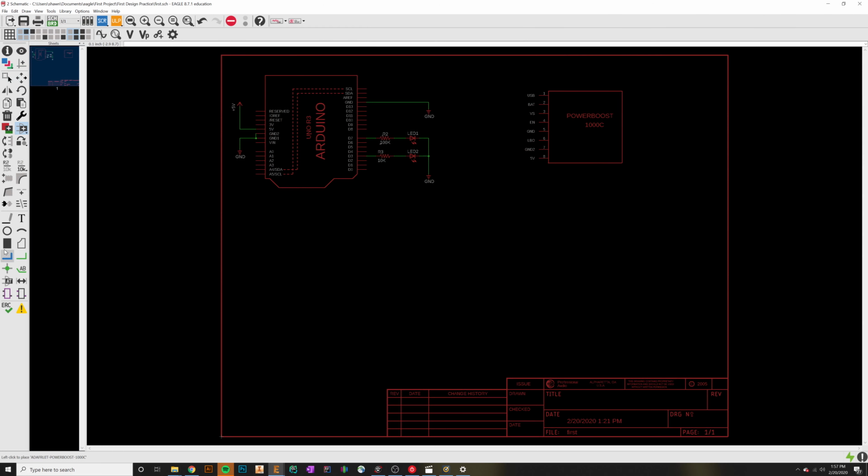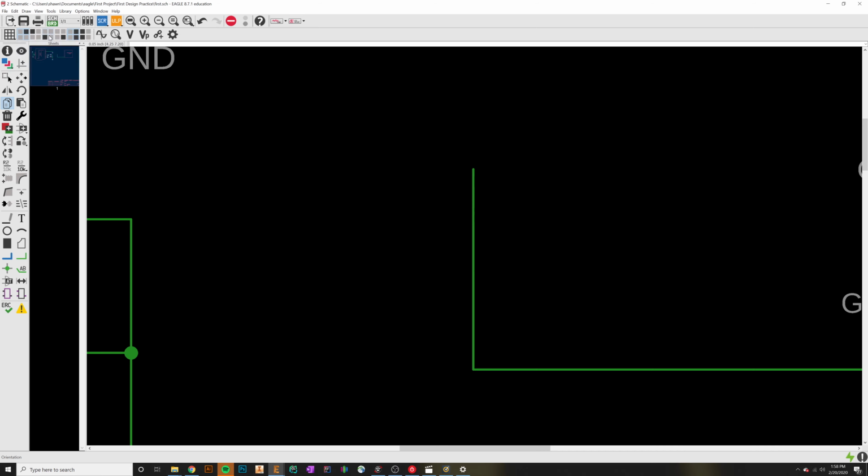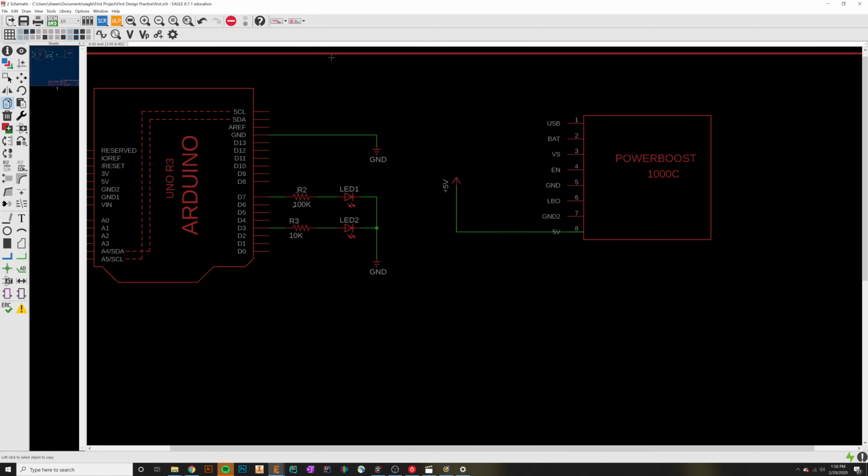Alright, so I'm just going to try to start creating some connections to it. You'll see that when I do this right, I can copy the 5 volts to here. Notice that this may happen sometimes where you can't physically connect it. You need to change your increment down. We'll change it to 0.05, which halves it, and now you can see it will make the connection. Alright, and the last connection I'm going to make is this little ground connection. And I'm just going to copy my ground and paste it right there.